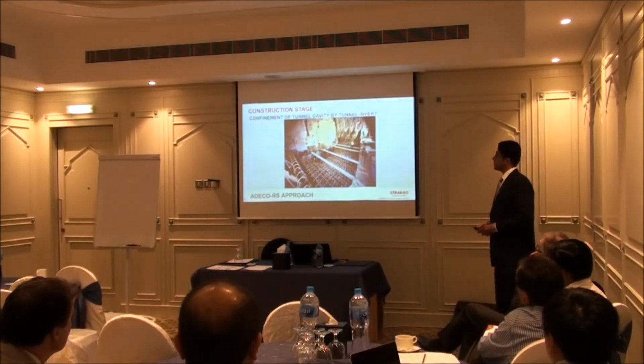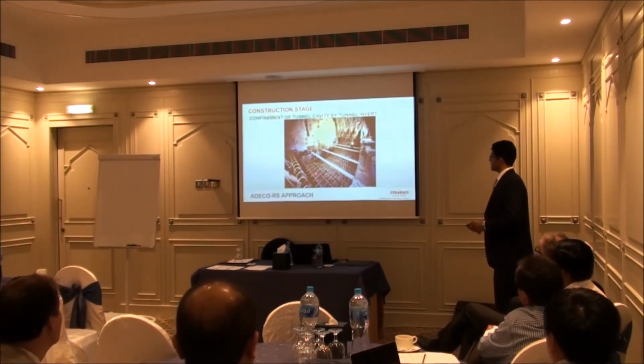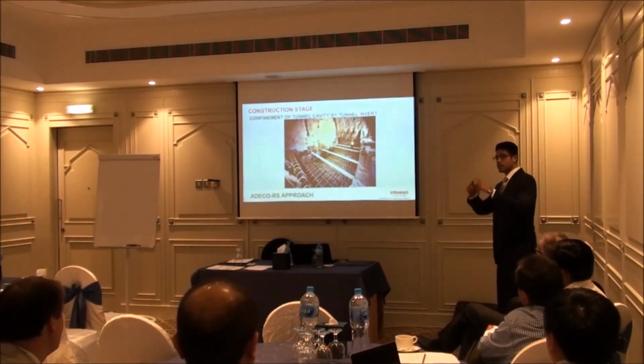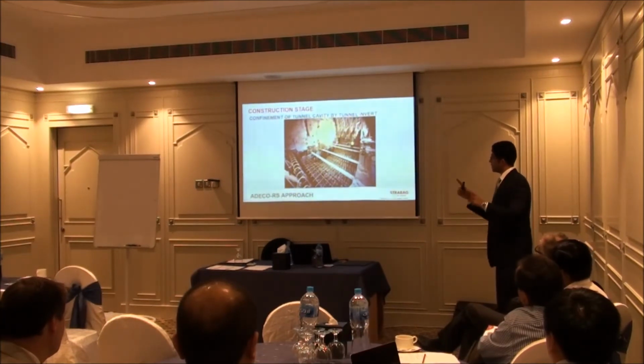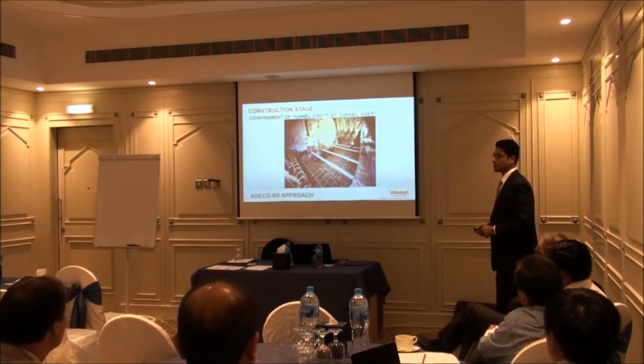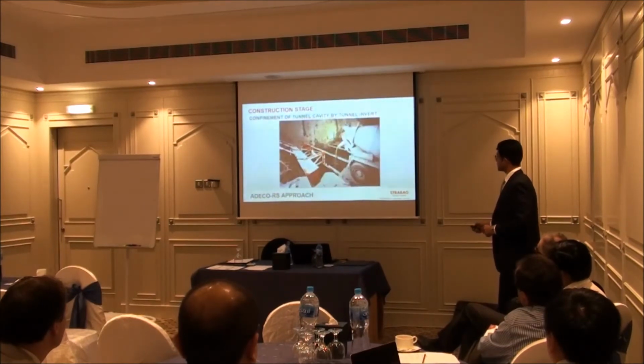This is the casting of the tunnel invert. The tunnel invert is also used as a method of confining the cavity, because it gives stability by closing the ring of the arch. So it is important in the ADECO RS method to keep the tunnel lining as close to the tunnel face as possible. Another view.